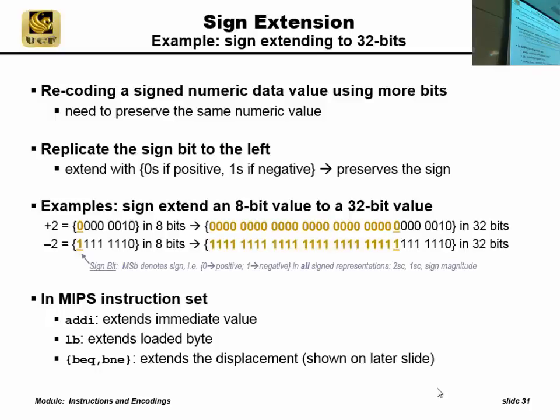Does everybody see why we need sign extension? Sign extension is needed anytime you want to convert one bit format to another. We can't just always write 0s. If we're in module 3, no problem. When we get to this module, we're working with negative numbers too. Negative numbers need leading 1s.